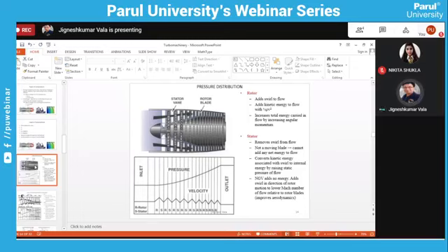And heat flows from higher temperature to lower temperature, naturally. The first law does not really say that such a process is not possible, and the second law brings in the directional aspect. You can actually take water from the ground floor to the top of a multi-storied building by using a pump, but that means you have to put in an external agency to supply the work. So these directional constraints are added by the second law.